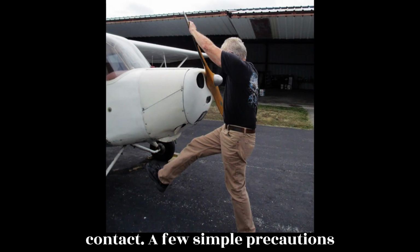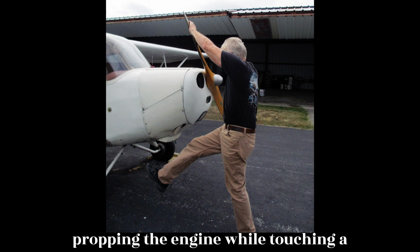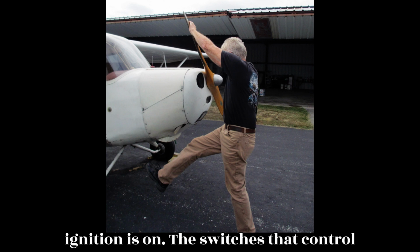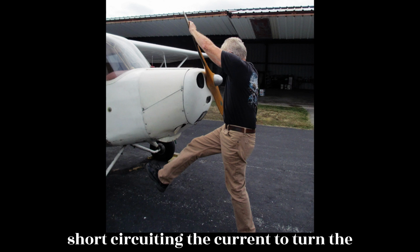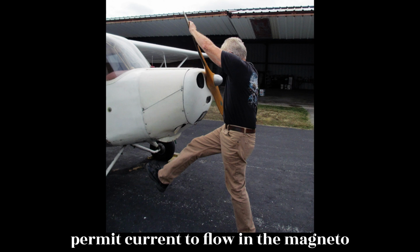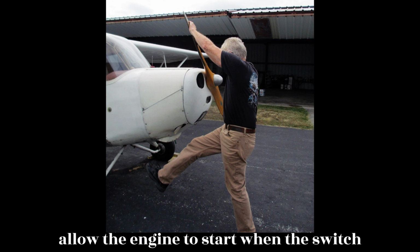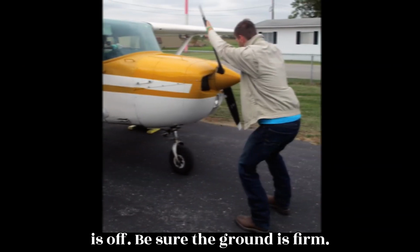A few simple precautions help to avoid accidents when hand propping the engine. While touching a propeller, always assume that the ignition is on. The switches that control the magnetos operate on the principle of short-circuiting the current to turn the ignition off. If the switch is faulty, it can be in the off position and still permit current to flow in the magneto primary circuit. This condition could allow the engine to start when the switch is off. Be sure the ground is firm.